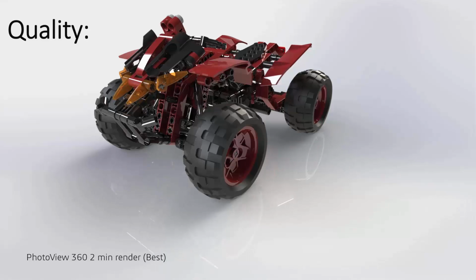Where you do see the difference is in the transparency. So that's pretty typical. These settings do index up your reflection rays and your refraction. So maximum is 10 and 10, best is 8 and 8. So you see that bump down. So we do see a difference there, where the reflections usually come out quicker than the refractions do.